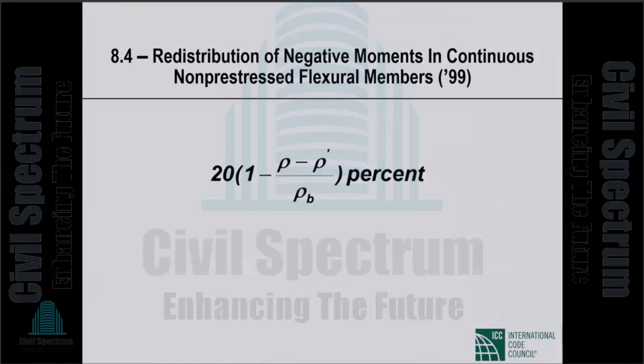The ACI 318 edition before that was 99, 318-99. So in the slides that I'm skipping, I go back to ACI 318-99 to tell you what the problems were, how we failed to treat reinforced concrete and pre-stressed concrete beams and columns the same way, which was in Bob Mast's mind the justification for unified design.